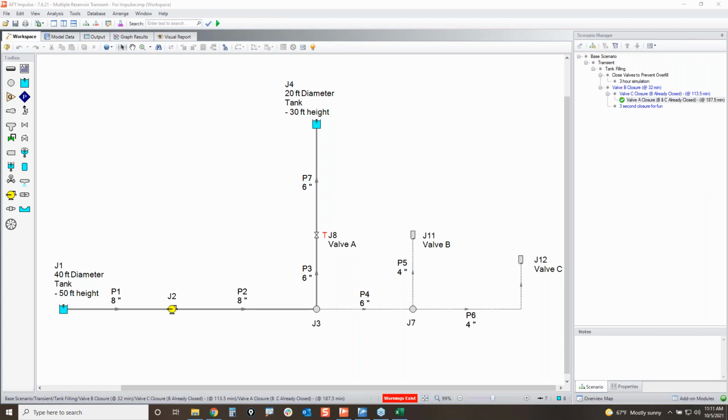Again, that is modeling long transient simulations, and every time step is a steady state solution. Keep that in mind, it is not accounting for the wave speed of the fluid in any way. It's missing all that information. Impulse you need for doing a water hammer or surge analysis, that is for sudden transients.